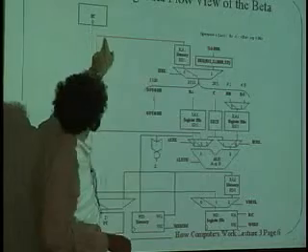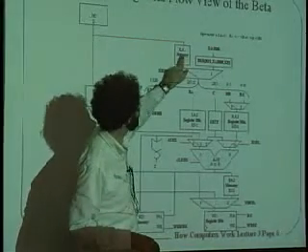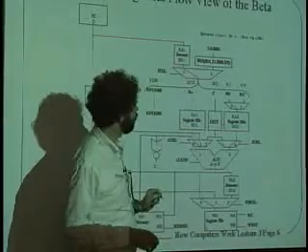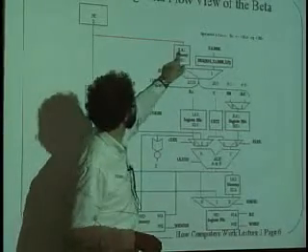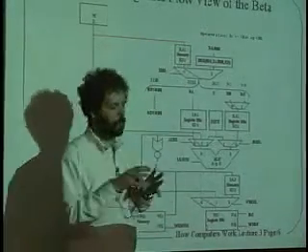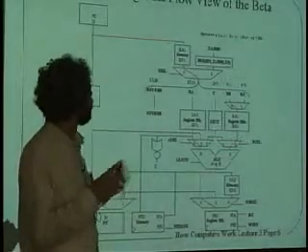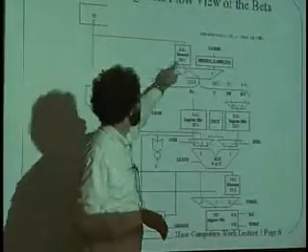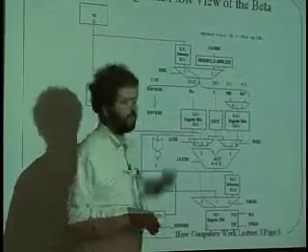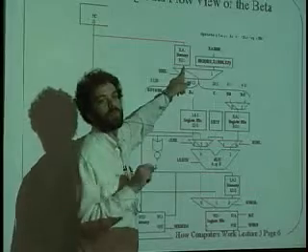The PC also goes out over to here and goes into the memory. And notice the memory here actually has several ports. Here's one. Read address 1 is an input here, and read data 1 is an output here. And so this is one port to the big, slow memory. And whatever address you put in here, the memory looks up the contents of the address that you give it and spits out the data corresponding to what's at that place.